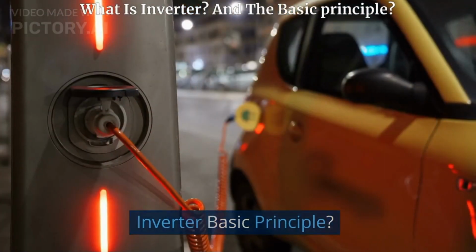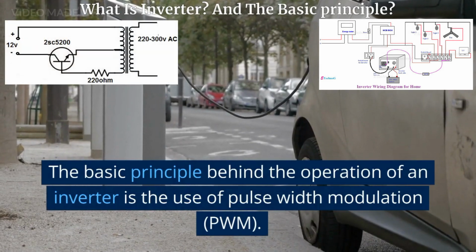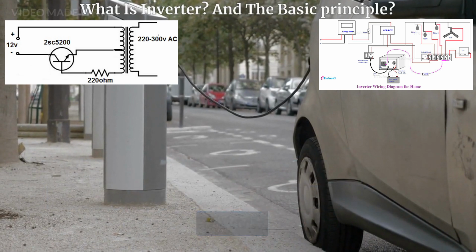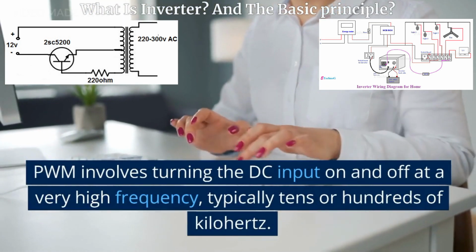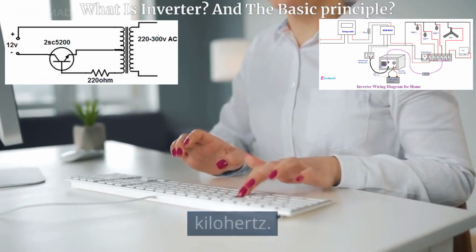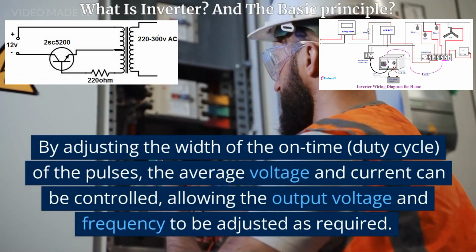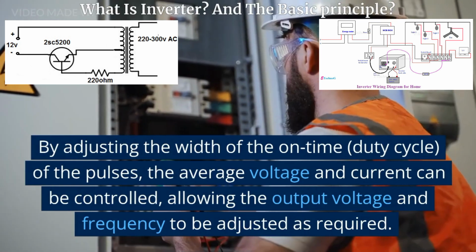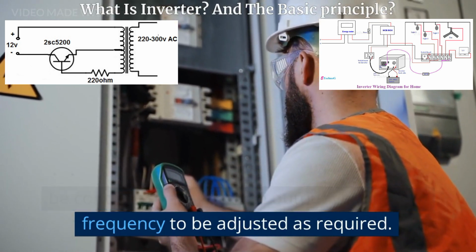Inverter basic principle. The basic principle behind the operation of an inverter is the use of pulse width modulation (PWM). PWM involves turning the DC input on and off at a very high frequency, typically tens or hundreds of kilohertz. By adjusting the width of the on-time, the duty cycle, of the pulses, the average voltage and current can be controlled, allowing the output voltage and frequency to be adjusted as required.